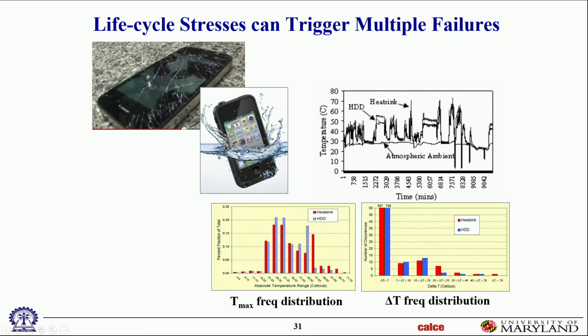The question is, even if I collect it, what am I going to do with it? That's a horribly complicated looking piece of information. How do I convert it into something that a CAD tool can use, so that with that information I can tell you how many such days this product is going to last? How do I extract useful information out of that for the CAD tool? Well, that depends on what inputs your failure models or design models need. For example, many of the failure models we use look at that and say, oh, that's cyclic temperature, that's cyclic expansion and contraction, that's cyclic fatigue loading.